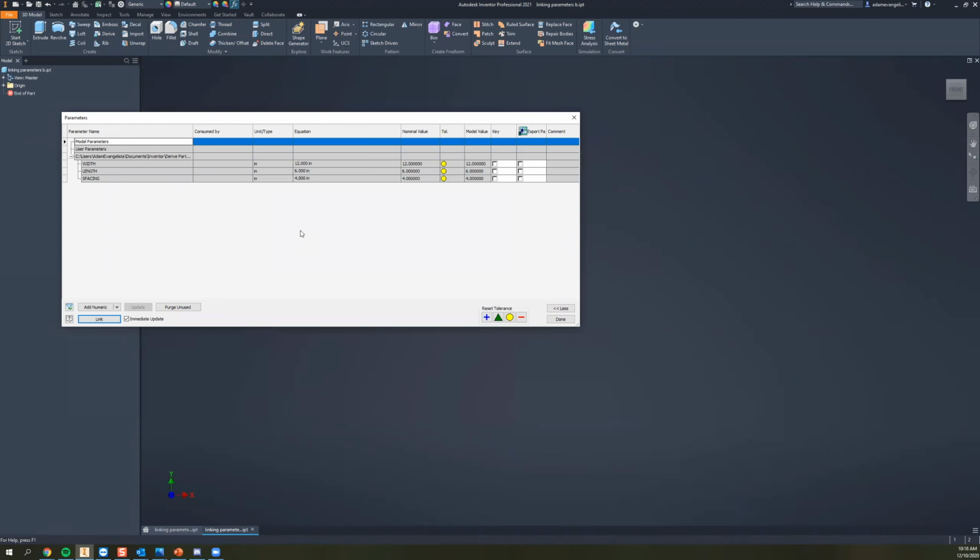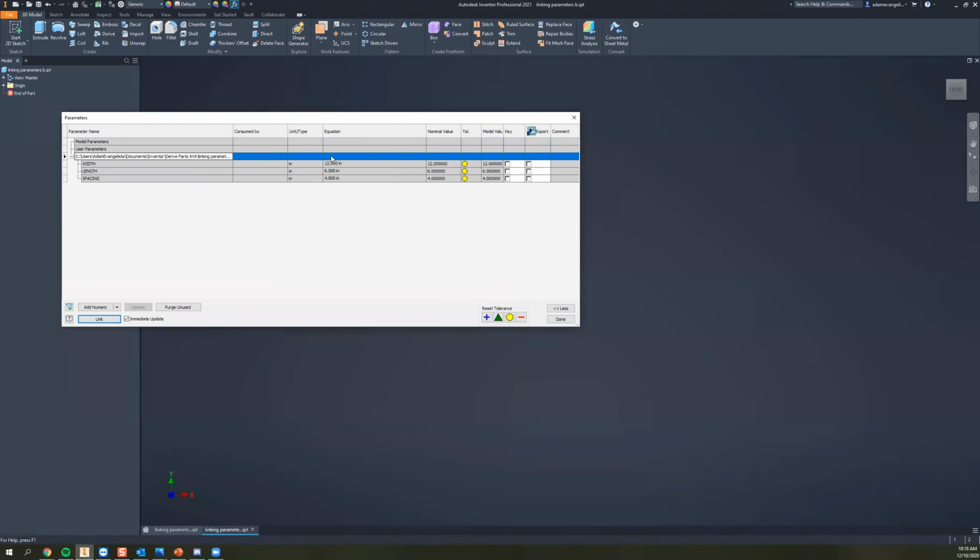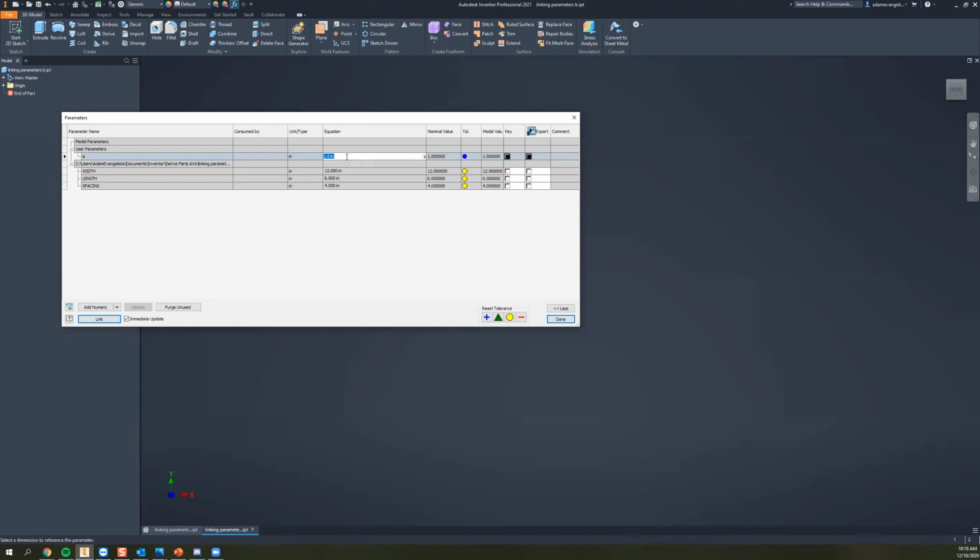And at this point, these two parts are linked together. And I'm kind of rushing through this just because it's a pretty simple thing, right? It has a direct file path to another part, and you could essentially choose which parameters are going to be usable in here, right? And so now I could even use these parameters inside of my own new numeric ones over here. So, you know, I could call it A, and A is equal to, you know, width minus 1 or something. And so we expect that nominal value to be 11, right?